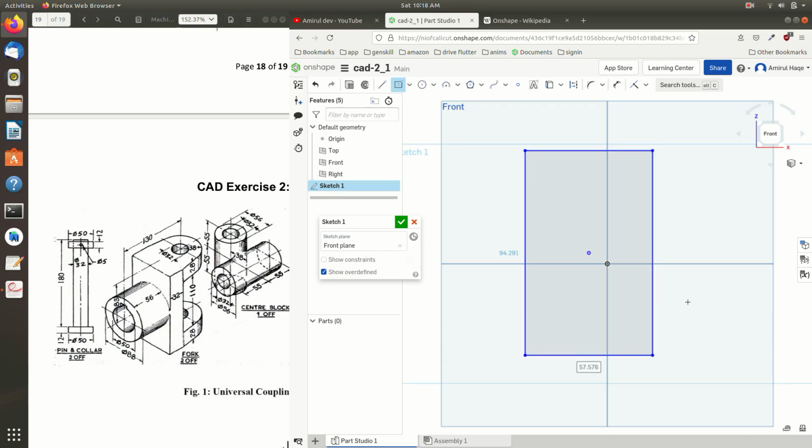So just make a rectangle, and then we need two circles, right? This is the view we are taking. We have a rectangle, and then two circles. Let me take a circle and place it randomly, and one more circle, placed randomly. From this view we will also get these two flanges, or projections. We'll have a small rectangular sketch here, with a width of 28.